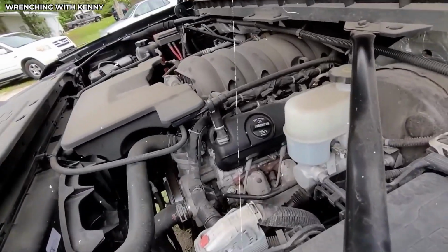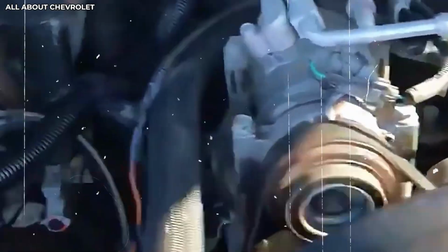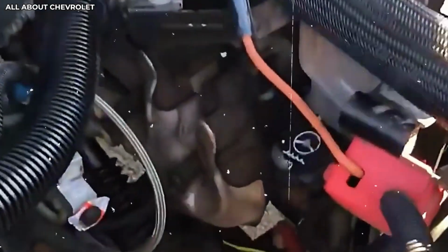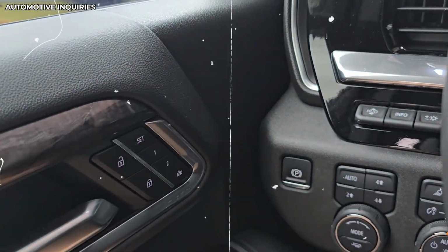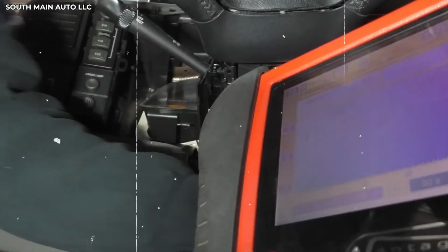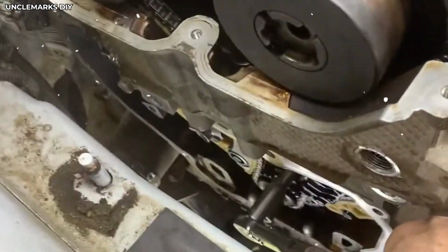Fifth, on turbocharged engines, aggressive driving after a reset means the turbochargers will spool harder and more frequently than they have been. If your truck has high mileage or hasn't had regular oil changes, suddenly driving hard could expose existing turbo bearing wear that was masked by conservative calibration. Make sure your maintenance is current before pushing a high mileage EcoBoost hard.